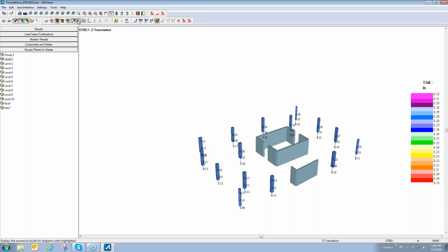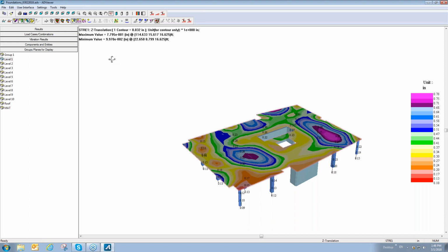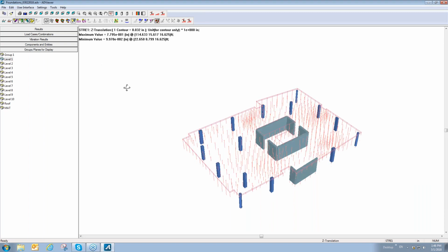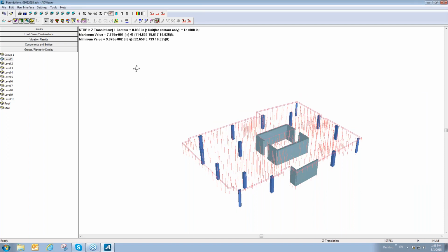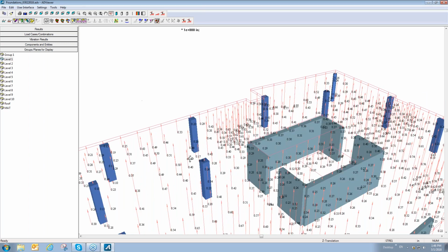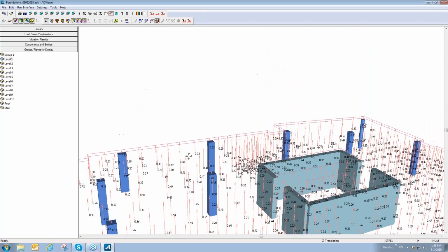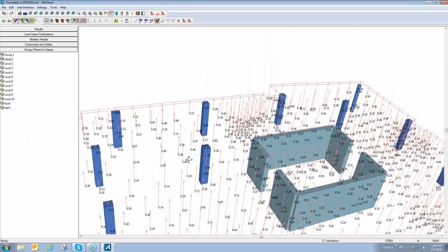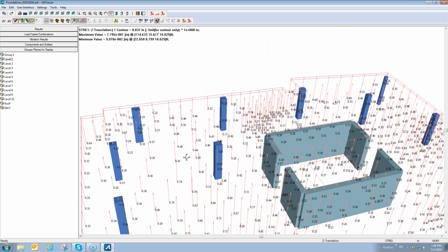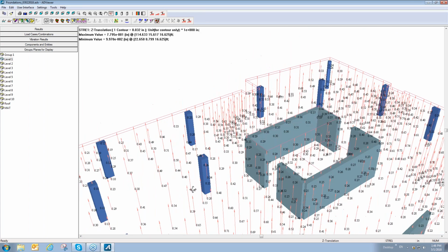point displacements. For the slab itself, what I was trying to show earlier at a mat, which I'm not as familiar with, is if you go to the vector plot, the vector plot should show you the values for displacement. It's just not turning on. I don't know why. Let me see if that was, yeah. So this will show you displacements at nodes, at pinpoint locations, but it's at the locations of a node that we use for the mesh. So that's one thing you can look at and use if needed.